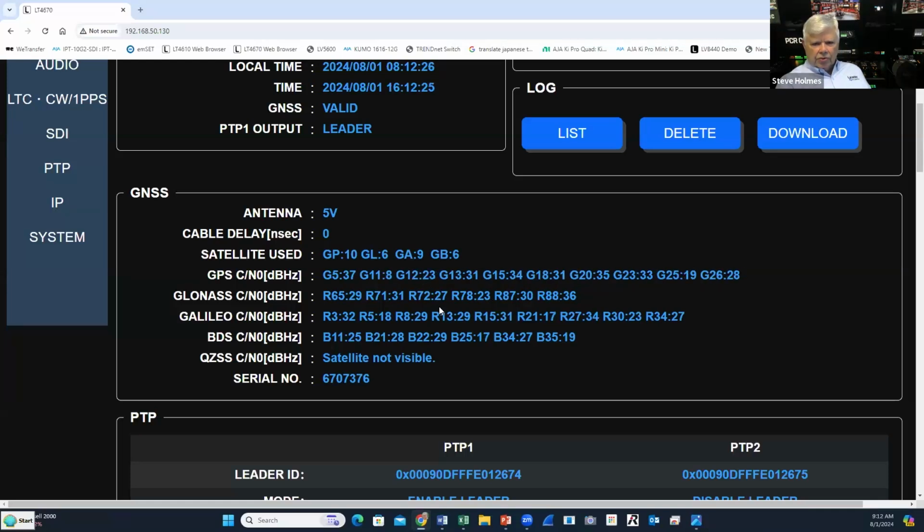Satellites are in a low Earth orbit, so they are not geosynchronous. They are moving. So a satellite moves in, the satellite moves out of view, and you'll see them pop in and out. And one of the very unique things here is, for the US system, I've got 10 birds I'm looking at. For GLONASS, I've got 6 birds I'm looking at. For Galileo, I've got 9 birds.